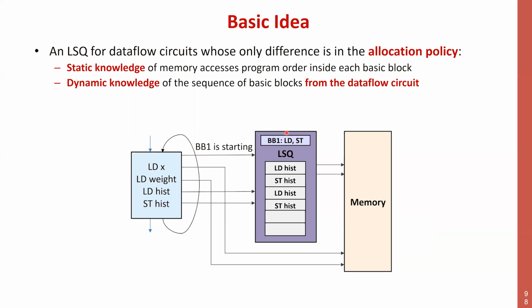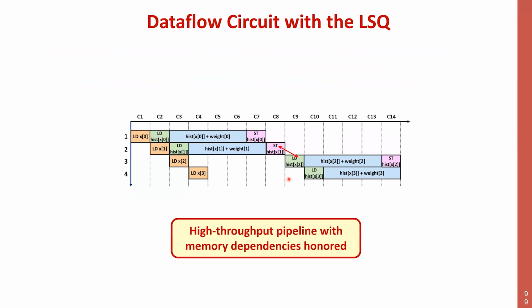Apart from this, the queue now works exactly like the queue that I have, that will let loads execute before stores only if they don't collide, and which includes the fact that I know exactly their addresses, and so I can safely execute them before the store.